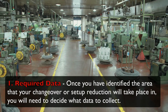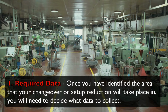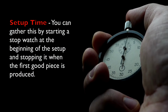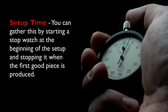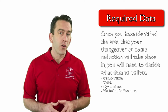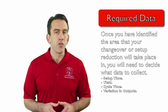Phase 1 is the required data. Once you have identified the area that your changeover or setup reduction will take place in, you will need to decide what data to collect. At the heart of a setup reduction is your setup time. You can gather this by starting a stopwatch at the beginning of your setup and stopping it when the first good piece is produced. Some other suggestions for data you might want to collect are yield, cycle times, and of course, any types of variation in the changeover.